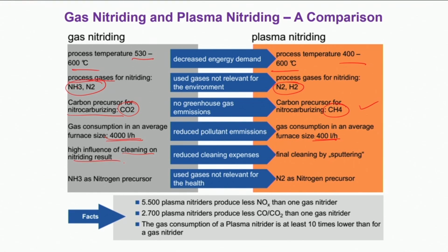Prior cleaning to the treatment is very important, because in any of these high temperature processes of iron based components, why only iron, let's say titanium or chromium or all these metals are very prone to formation of a very thin oxide layer onto the surface. In case of iron, this is a very major tendency. When these oxides form, they act as a barrier for any ingress of gaseous atoms from the atmosphere.